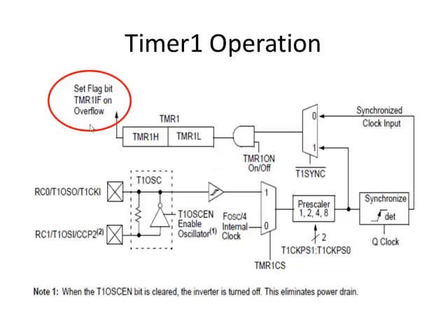Okay, remember I talked about what happens if the timer times out, which means that it goes from all ones and then you get one more clock pulse in. Well, it rolls over to all zeros, and then the overflow flag will be a 1. Okay, so there's a bit in one of the control registers called the TMR1IF. Okay, make sure you spell that correctly in software. TMR1IF, that's a capital I, capital F.